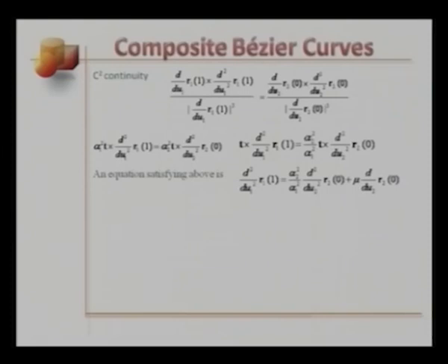Well, you guessed it right. It is 0 because the direction of the unit tangent T and the first derivative of the second Bezier segment is the same. When I say so, I implicitly assume that the composite Bezier curve is a C1 continuous Bezier curve.